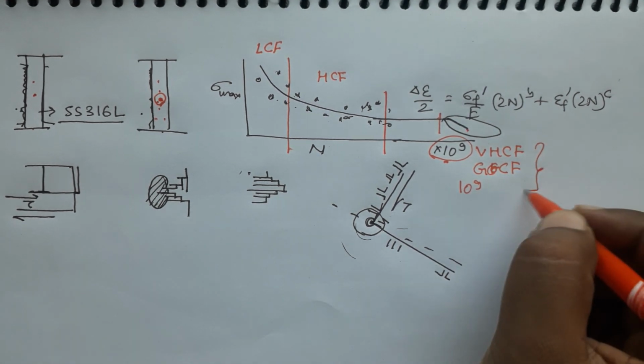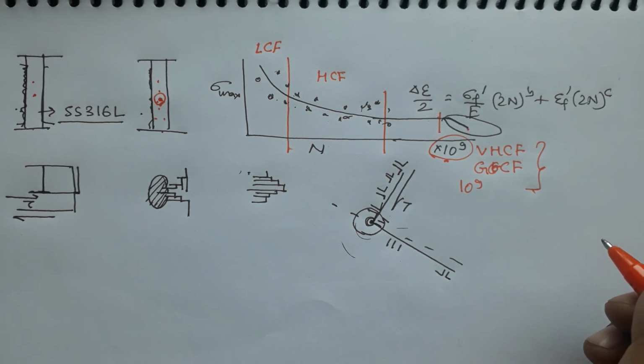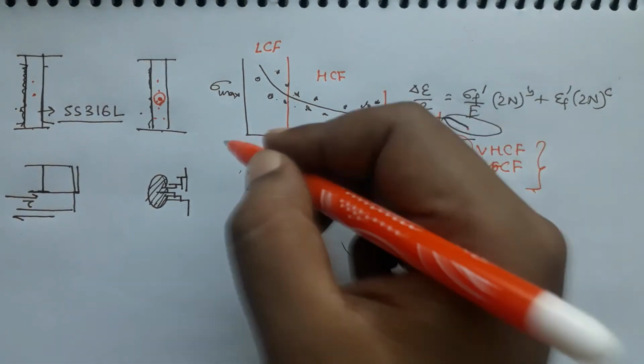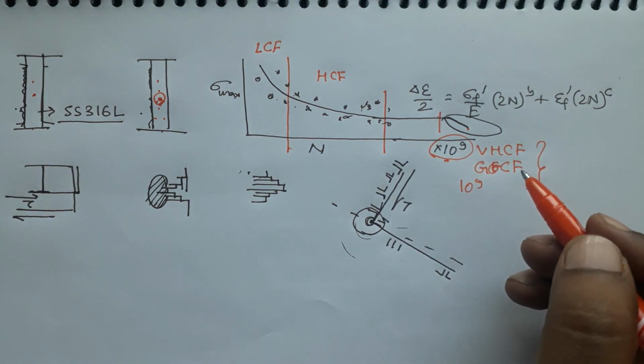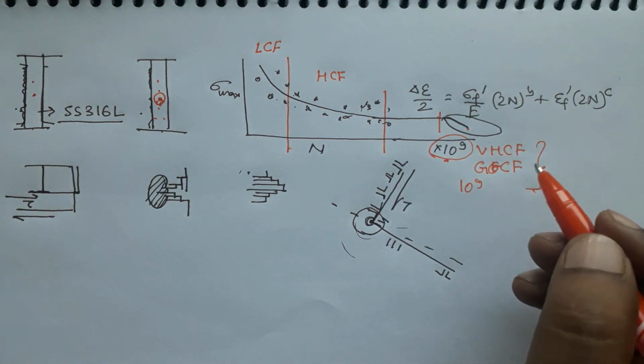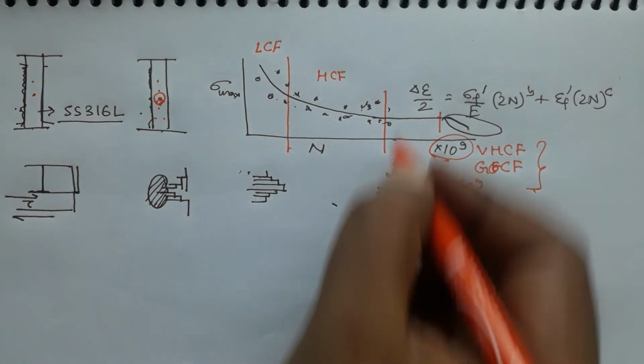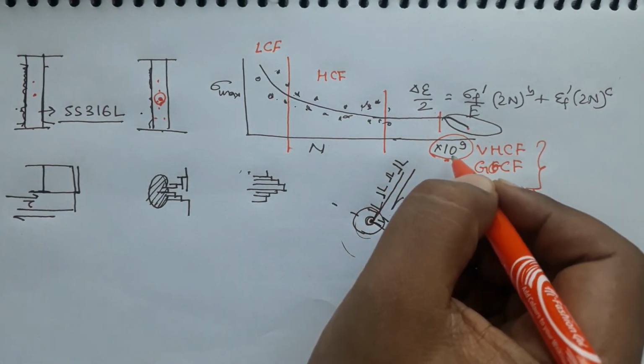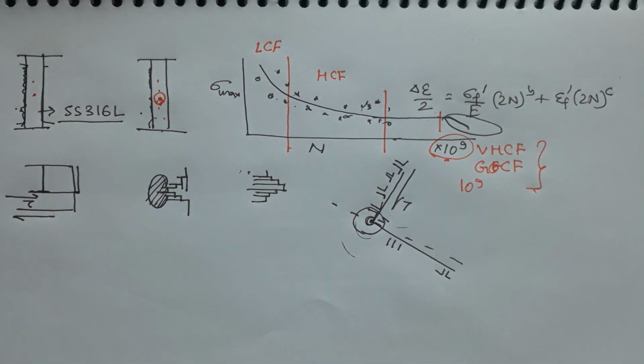So that is new research, which showed the world that there is no endurance limit for any kind of material. There is no true fatigue limit, but you can call it a fatigue limit if your component is not going to be used for more than 10 to the power 8 cycles.